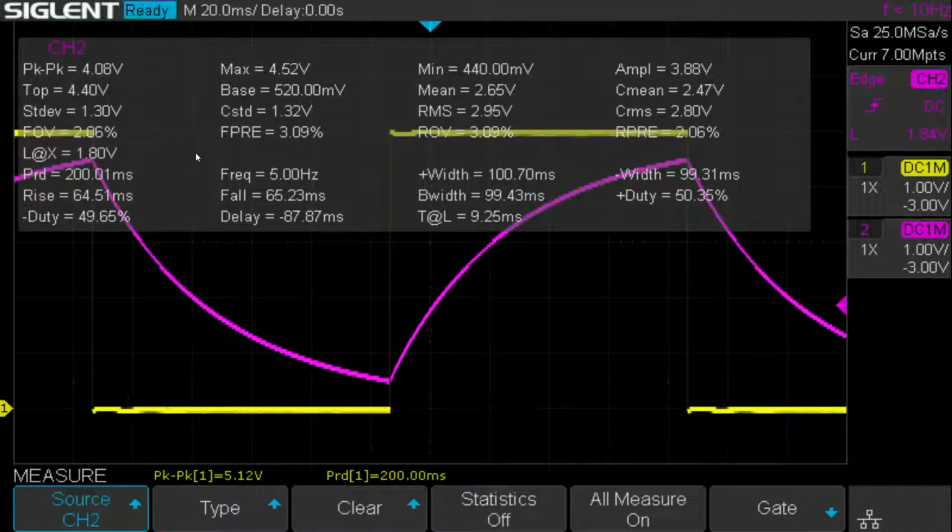So experimentation can also validate whether you're selecting the right components when you're doing your PCB analysis. That's another reason why doing these experiments is important. If you're selecting this capacitance and it's not producing the results that you want, most likely you've chosen a cheap capacitor and you want to go with a tighter tolerance, something that is close to what the simulation results are.